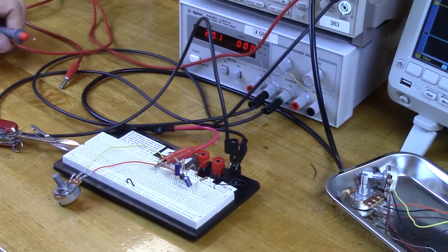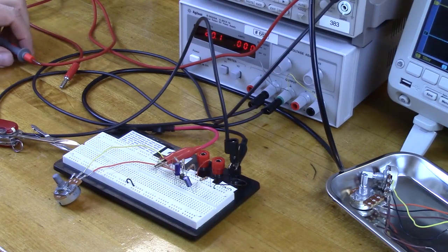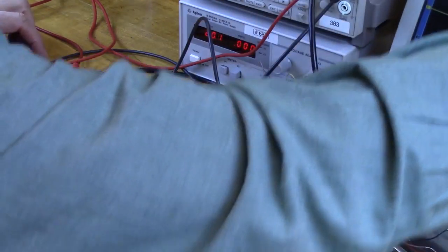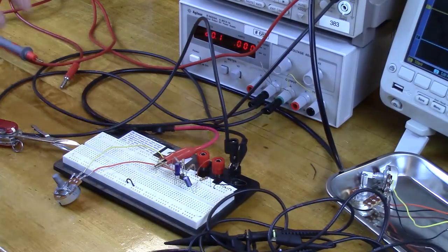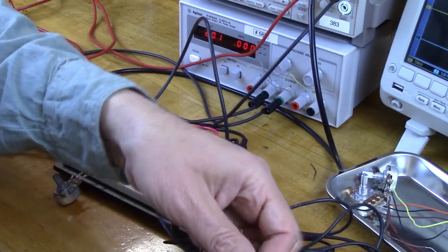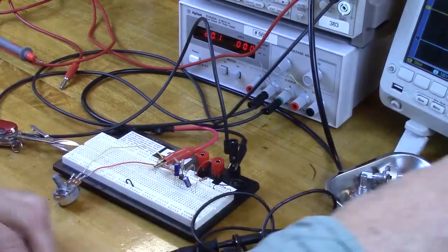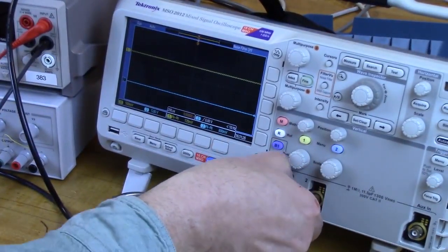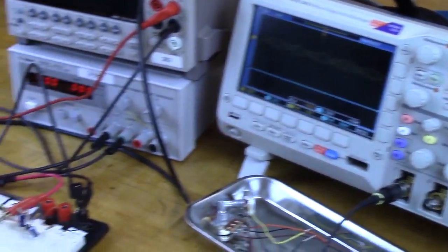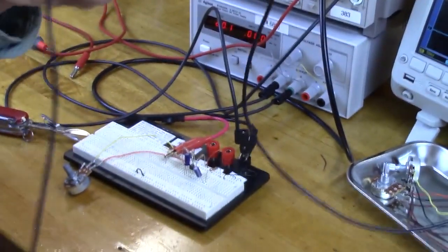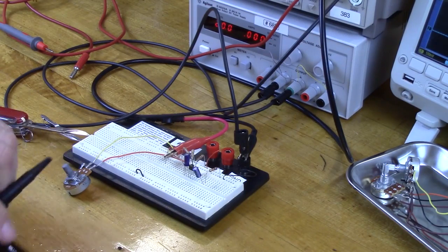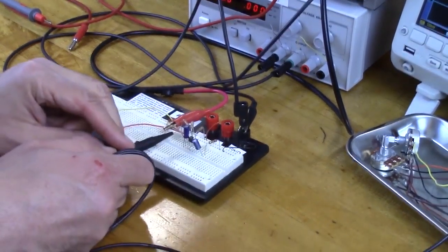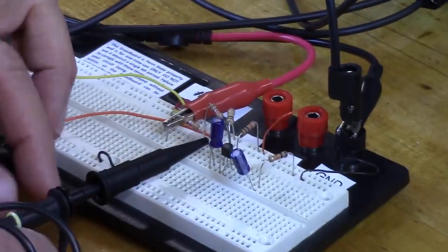And then all that's left is our scope. So we have our 2 scope probes back here. Oh yeah, somebody was being helpful in cleaning up. So the yellow one is channel 1. Let's just see where those unfurl. Okay, channel 1. And channel 1 is going to be connecting to the input voltage, which is the right-hand side of RS over there.